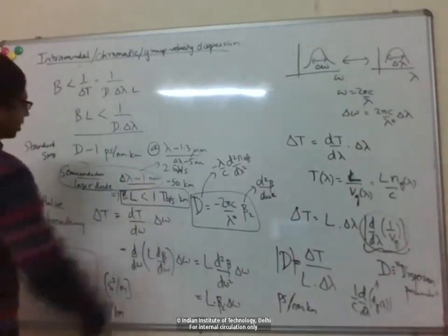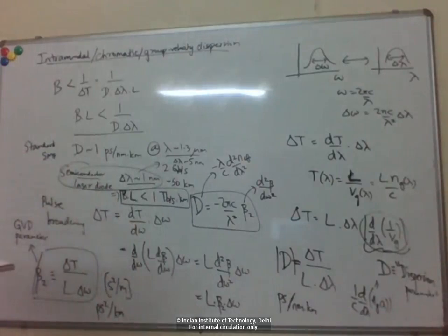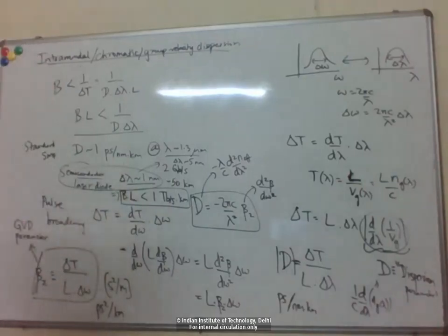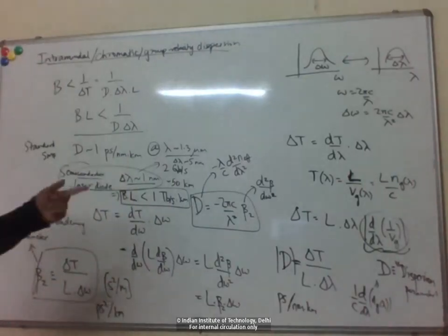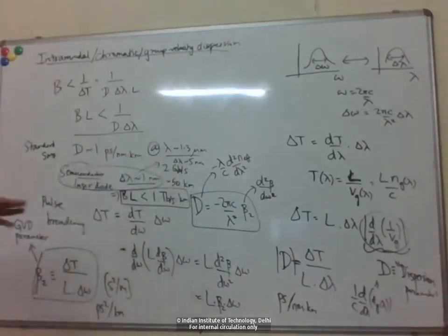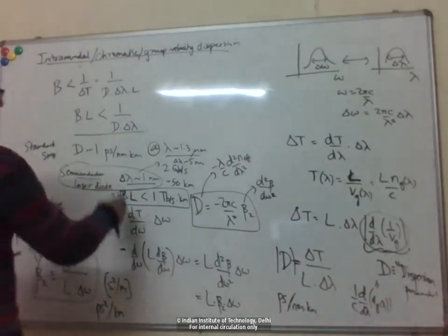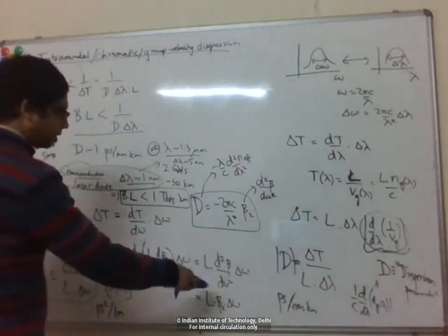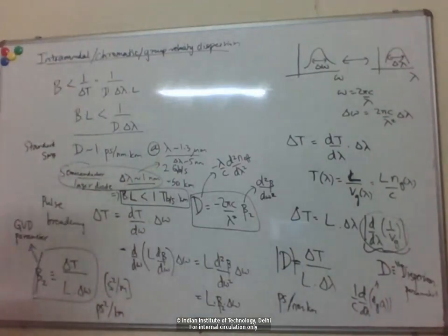Okay, so this was roughly the third generation of optical communication systems, right? And then in the fourth generation, we started compensating even for this chromatic dispersion, and started using external electro-optic modulators to boost this, and also optical amplifiers and WDM systems. So you can see that basically this dispersion parameter is how the group velocity varies with frequency or wavelength.